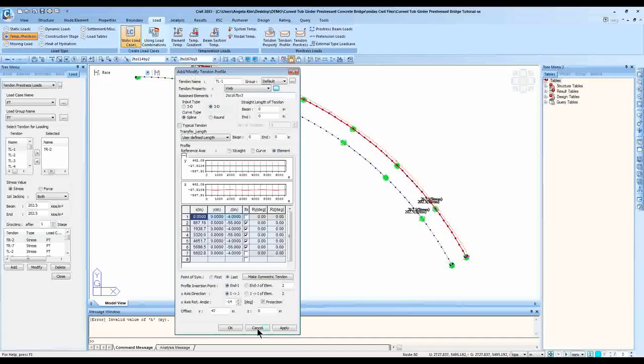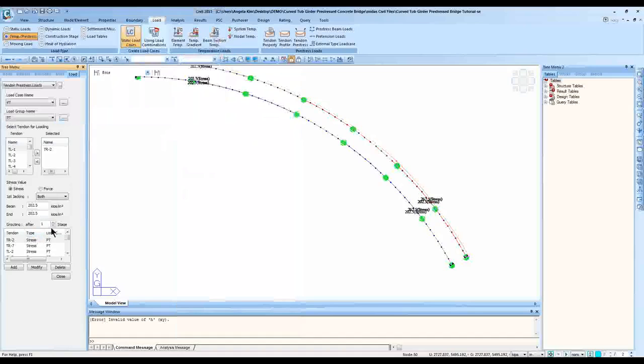And then assigning when to stress it. And also, how do you know when to apply the stress and things like that? So when we define this tendon pre-stress load, you can also define the load group name. And load group. Does this sound more familiar now? So basically, you assign each pre-stress into a load group. They don't have to be assigned to different individual groups. You can actually define them in different groups depending on when you want to activate them.